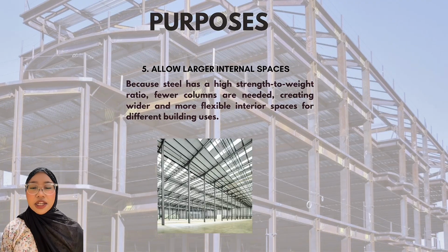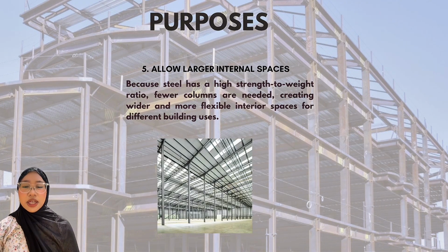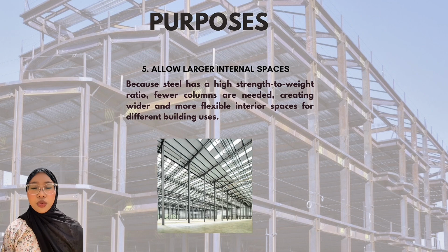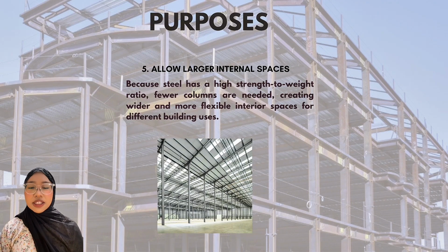Lastly, a steel skeleton frame allows larger internal space. Since steel has a high strength-to-weight ratio, fewer columns are required to support the building. This creates wider open spaces, giving architects greater flexibility in designing the interior layout.